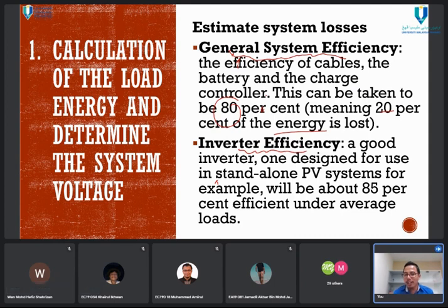Okay, that's why we don't really care about the inverter efficiency. Even though it is written in the description, we don't cross-check because we are looking for the cheapest one. So please don't buy an inverter, even if they write pure sine wave inverter, if there is no appropriate datasheet. Better to avoid. Even me, I will also choose the cheapest one. But please, if you want to buy from an online shop, cross-check between the description and the original datasheet, and also ask the seller, because it's about money. It's about your cost. The inverter efficiency is quite critical.